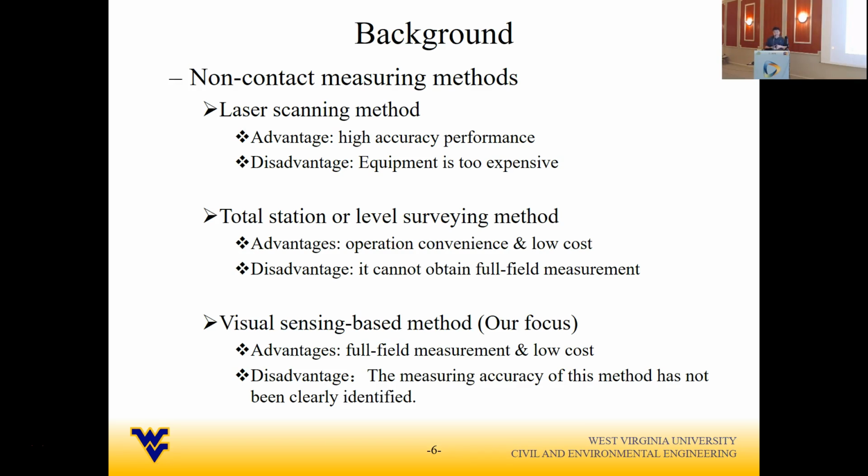The second class of technologies is non-contact measurement methods. The first one is laser scanning, and the majority of you are very familiar with this technology. Basically, it generates a dense point cloud that's very accurate, and measurements could be taken on top of it. The very high accuracy is the benefit of it. And of course, the downside is the equipment is bulky, and to our knowledge, the equipment is expensive.